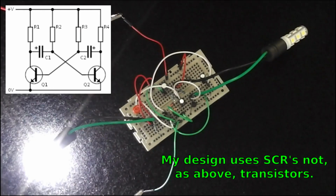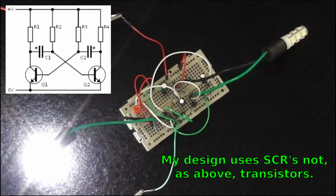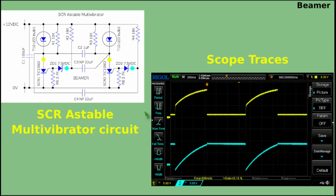So let's now have a look at my design, my schematic of this multivibrator and its associated scope pictures. This is more or less self-explanatory. The top left-hand side represents a circuit diagram of my SCR Astable Multivibrator circuit, and on the lower right-hand side this represents the scope traces. The yellow trace is the anode of both of these SCRs, and the blue trace here represents the cathode of these Zener diodes.